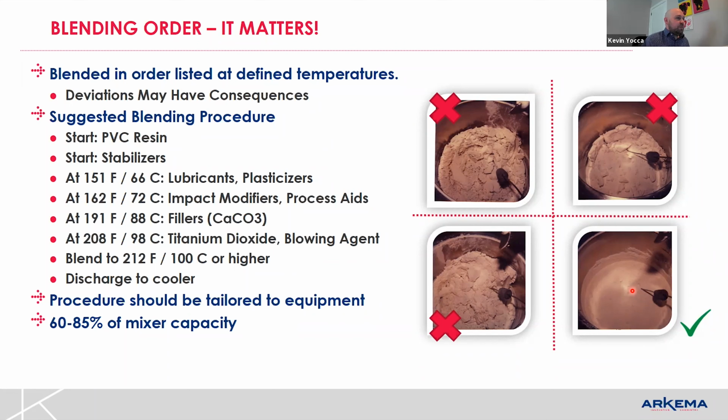After that, you see lubricants and plasticizers are coming next. Again, you want those next to the PVC because that's what you're trying to protect as you get through the extrusion process. Tin stabilizers will not help your weatherability, or well, they can affect it, but they're not primarily there to help your weatherability. What they're there to do is protect you during the processing so that at the end, you have as little degraded PVC as possible so that it will weather as long as possible.